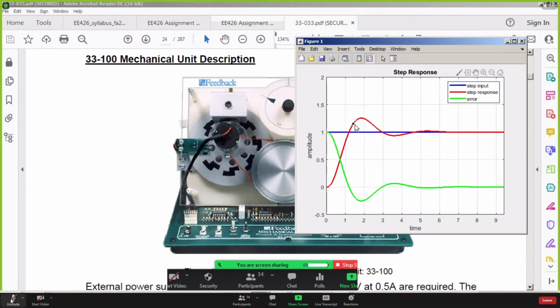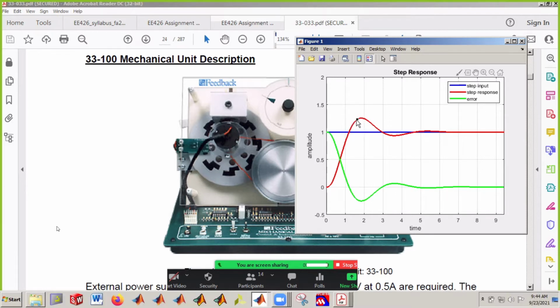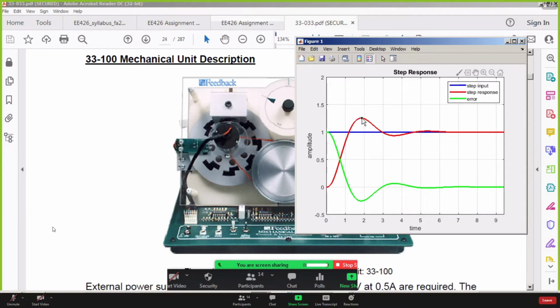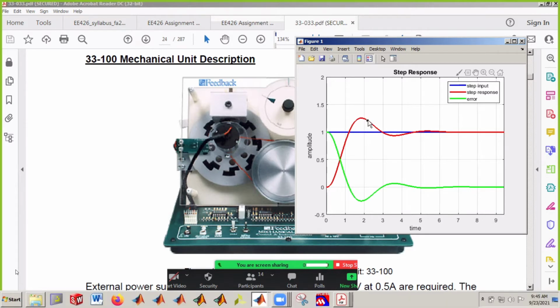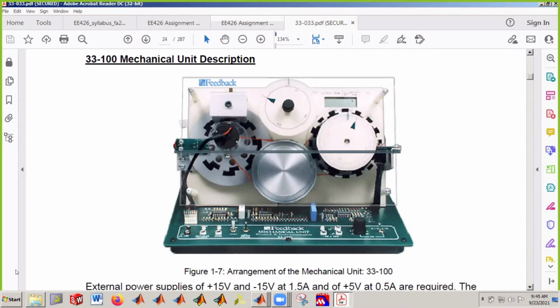How do we interpret this change here? Yes, very good. So this is how you would physically see this output, because remember, this is the position that you are seeing. Initially you go from 0 to a specific value where you have this peak. But eventually after this peak, it starts decreasing. That means the angular position is decreasing, which, if you are looking at the motor itself, you will see this thing reverse itself. Once you reach this peak and it starts decreasing, you will actually see the motor spinning counterclockwise.